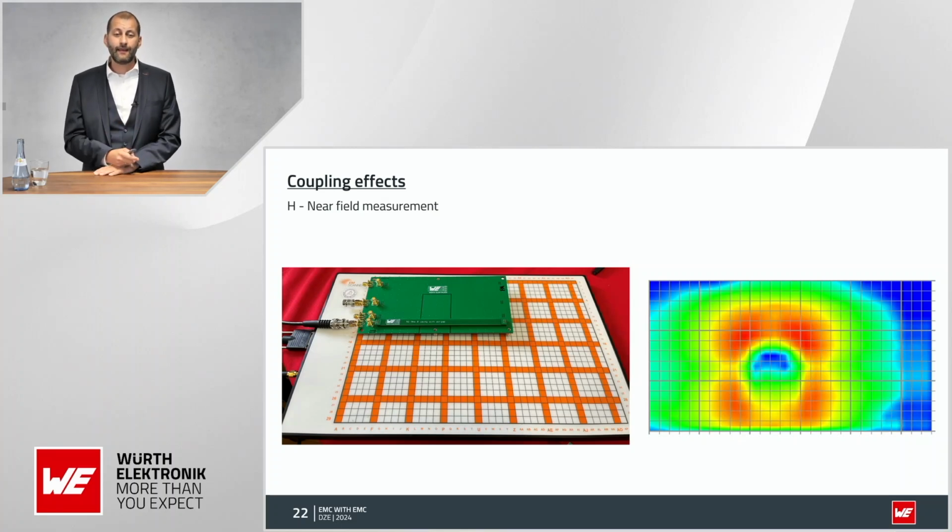In this case, in every rectangle you can see there's a really, well, sort of bad near field probe. What do I mean with bad? It only measures the really near field. And by that you can see the outcome of the magnetic field that's going to be generated due to the cutout. The circuit board itself is quite simple. It's the easiest version you could create.